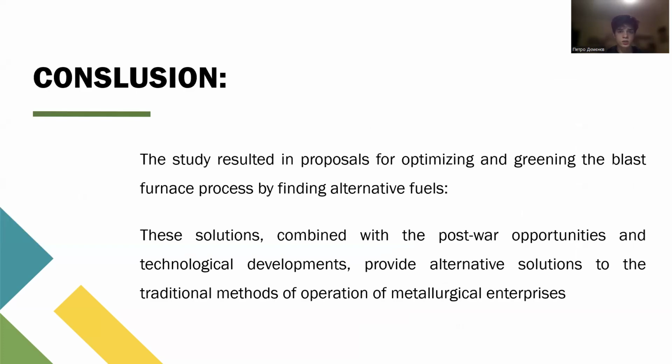The study suggests a way to improve the operation of blast furnaces by replacing traditional coke with alternative fuels. The use of anthracite and coconut as coke substitutes allows reducing costs and increasing process efficiency. The production of briquettes from metallurgical waste contributes to resource conservation. In addition to solid fuel substitutes, increasing the supply of natural gas and replacing it with cheaper coke oven gas allows for reduced costs and CO2 emissions, which makes these solutions optimal for the environmental friendliness and economic efficiency of blast furnace production.